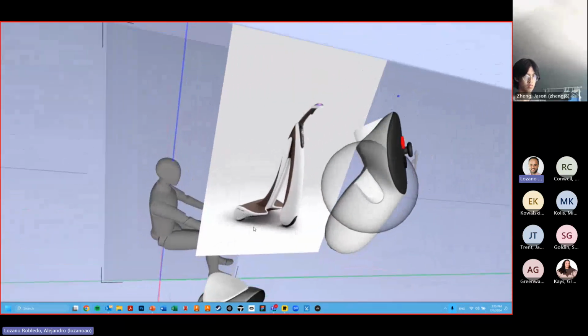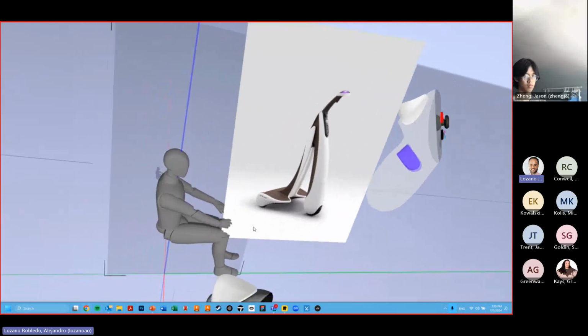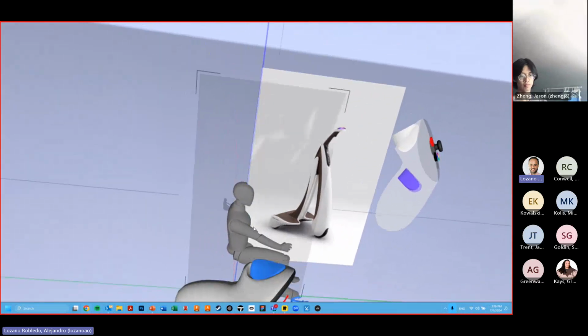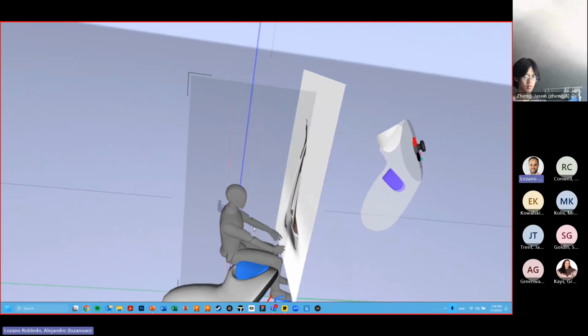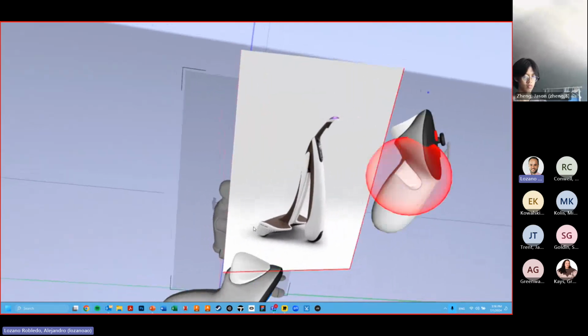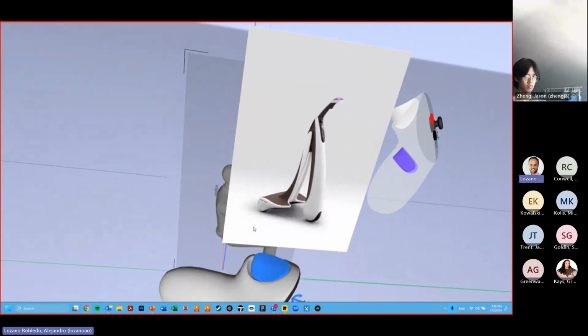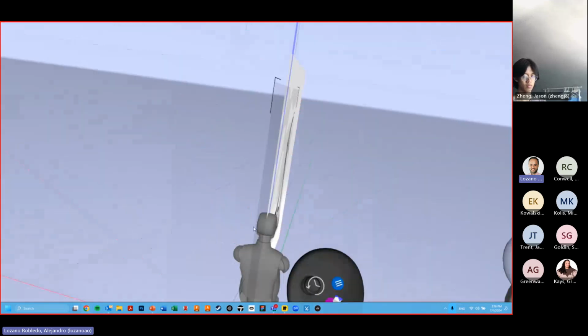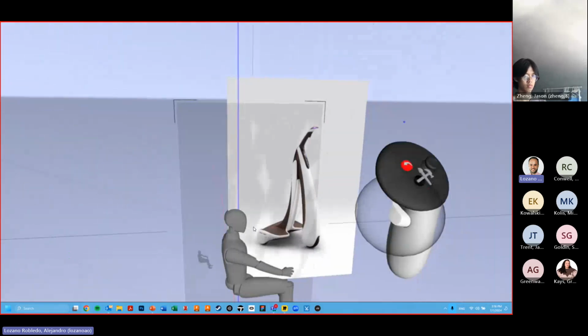In the recording, this will show. To grab, I use this button, but then with my left trigger, anytime I press it, it anchors it. So look at how it's forcing it to the mirror plane. I'm not having to do a big effort at that. If I press this left trigger, it anchors it. And if I release, this is exactly at the mirror plane, as you can see.